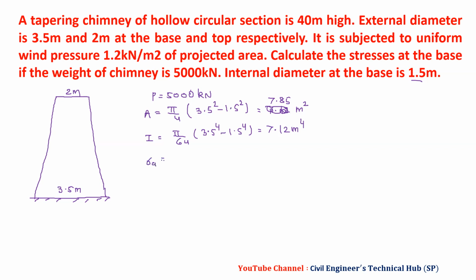Then sigma A is P by A. P is 5000, A is 7.85, and you have this value, P by A, 636.94 kilonewton per meter square.